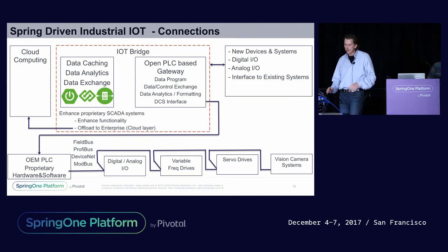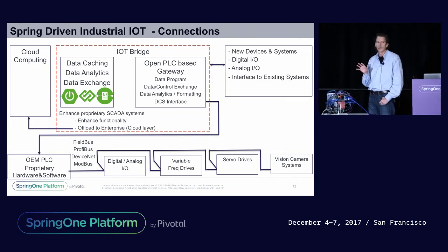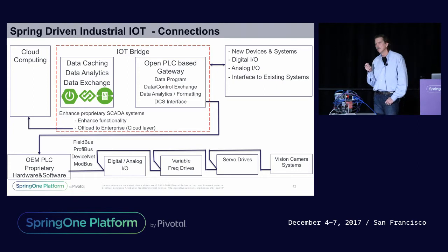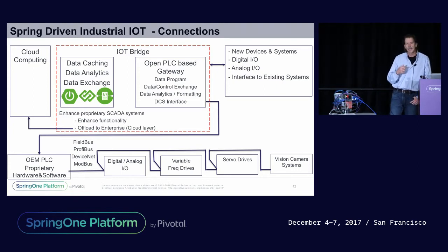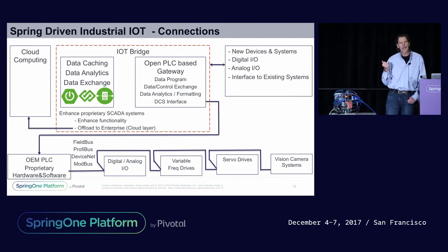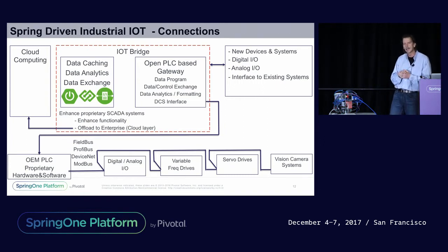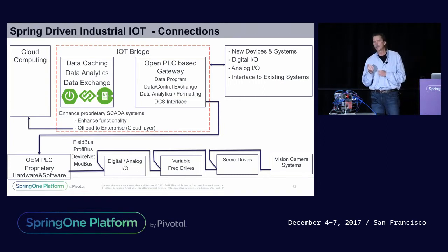So now down here at the low-level devices, the PLC, what is it going to control? The I/O. And that can be discrete I/O, 24-volt DC. It can be 120-volt, 230-volt. It doesn't matter. We can buy I/O, and if we need to change 5-volt, we can put some optical couplers on it, and we have it covered. And we can control the physical I/O, along with we can control motors, variable frequency drives, servo drives, any type of drives, things that run on field buses.